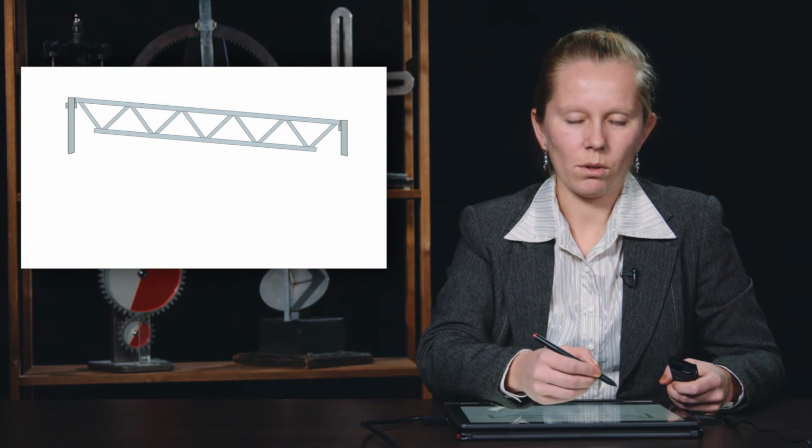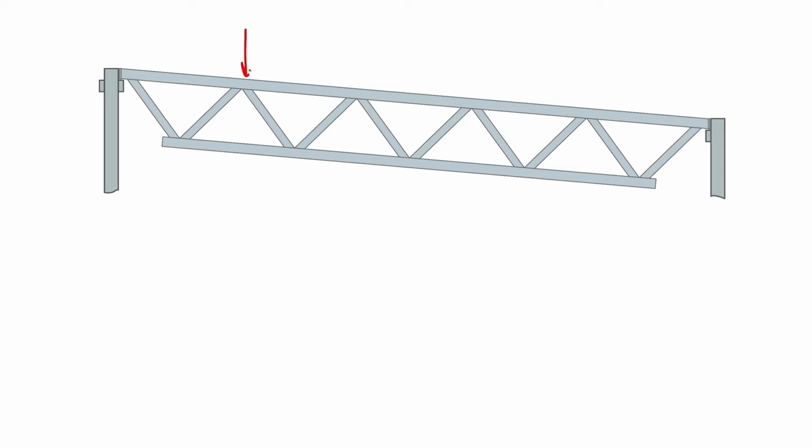The load on the truss exerted by the covering is considered to be concentrated in the joints. Because the load of the roof is distributed uniformly and the distance between any pair of the joints is the same, the forces are equal as well. The second assumption to be made in our calculations of the truss is that all the joints are hinged.